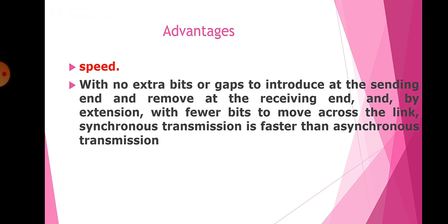Suppose you add a start bit and stop bit to the actual data, say start bit as 0 and stop bit as 1. At the receiver side, once again, we have to remove that stop bit and start bit. That is also an additional burden at the receiver side. Therefore, synchronous transmission achieves better speed compared with the asynchronous serial transmission mode.